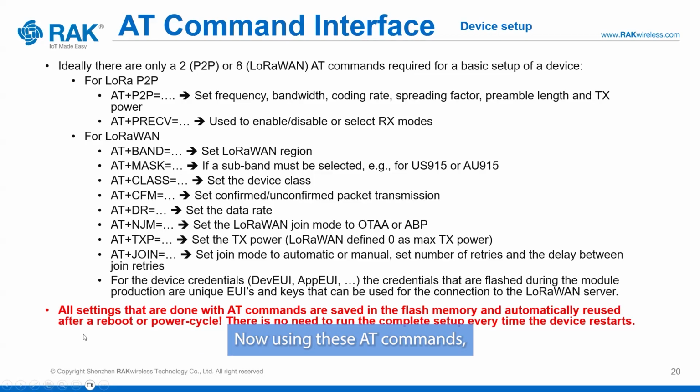Now, using these AT commands, settings are saved in the flash memory if they are changed, and they will be automatically reused after a reboot or power cycle. So this cycle of setup has to be done only one time. Then the module will have them saved and reused.